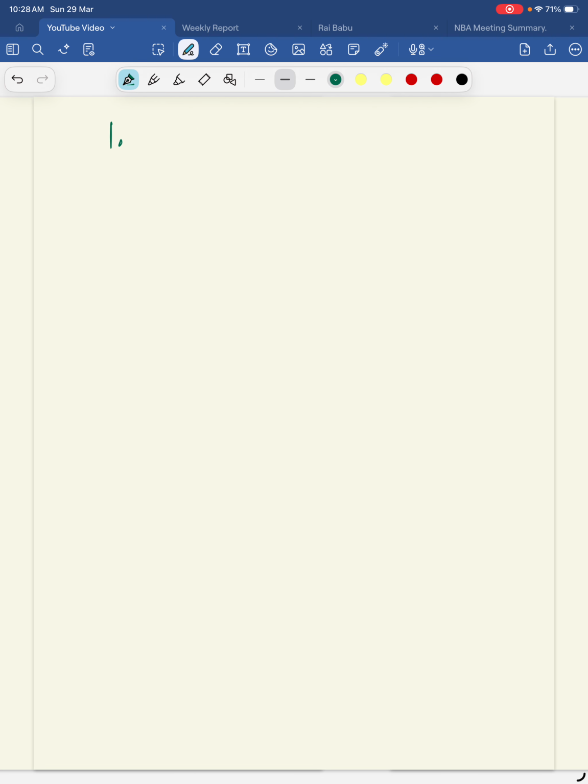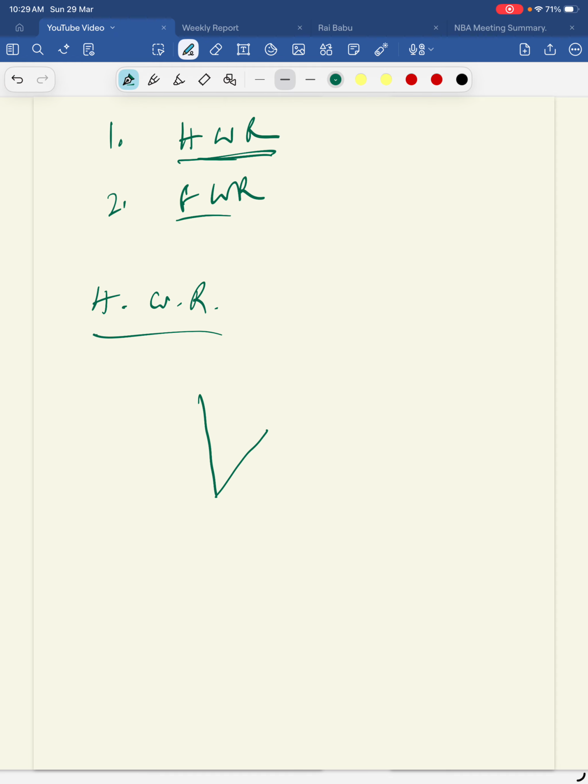As we know, we have two rectifiers, half wave rectifiers and full wave rectifiers. I will first discuss the half wave rectifier circuit. Let us draw the circuit diagram first to make you understand. For the half wave precision rectifier, as I mentioned, we will use an operational amplifier. This is minus, the inverting terminal, and this is plus, the non-inverting terminal. Suppose the non-inverting terminal is grounded.